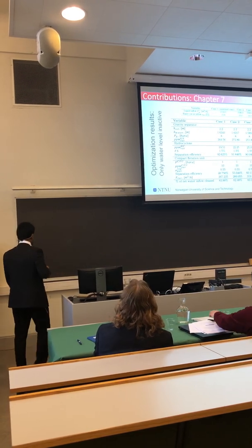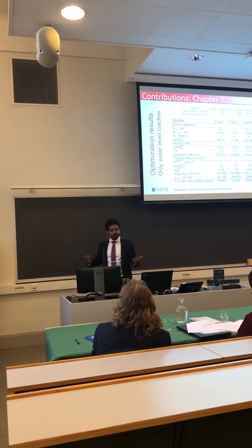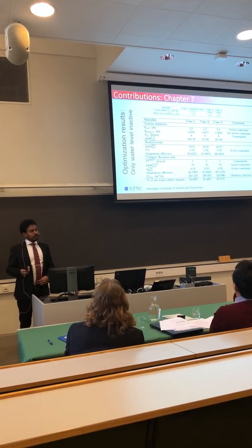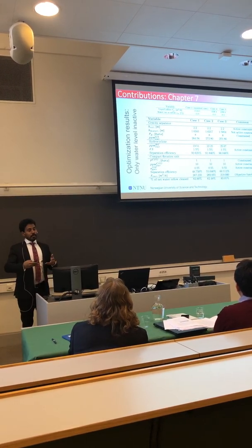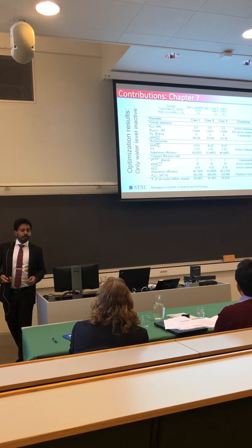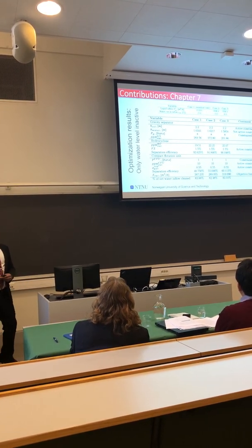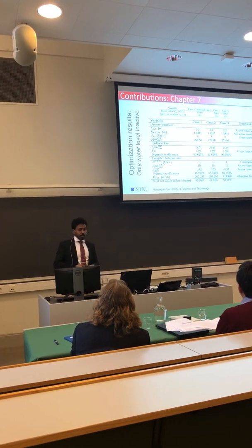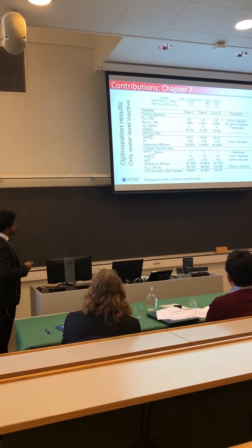And this is a typical scenario in subsea or in any separation in an oil field. It is very likely that at some point the separation system will have to go through a tie-in, when you tie in a different field or different well, and then all of a sudden the production goes high and the separation system has to deal with it. Also, very quickly the water content in the fluids starts to rise. So these are very plausible scenarios.